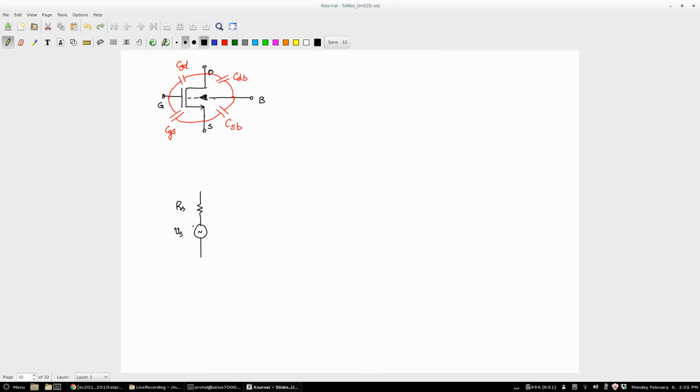So effectively what happens? Let me again keep this here. So the equivalent circuit that we have now, just to convey the point, I am going to draw it with the value of Vs and Rs. Keep in mind that this Vs and Rs are the effective Thevenin voltage and the effective Thevenin resistance. Now because your RL RB is much greater than Rs, effectively your Rs prime will be approximately Rs and your Vs prime is approximately Vs, right, because you have designed it such. So you don't need to really worry. And so these two things go in here.